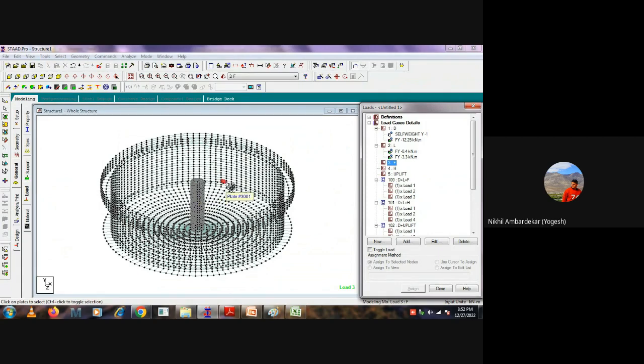So we have to again distribute it at very fine locations. Just to avoid that, because the space is very small, we can consider putting this 9 kilonewton or maybe 3.3, so that it is taken care of. Or, a better way, you can directly consider a 3 kilonewton plate load and apply it here also, as uniform pressure. That can also be fine. Okay, sir. Okay.